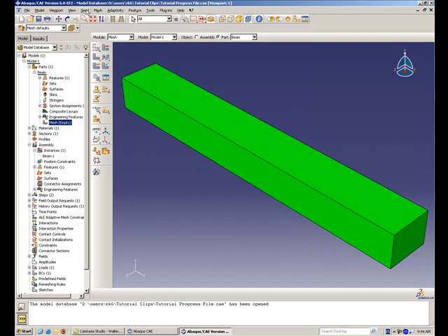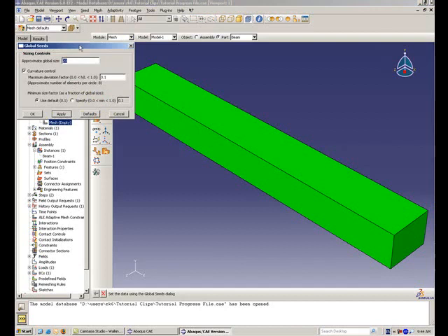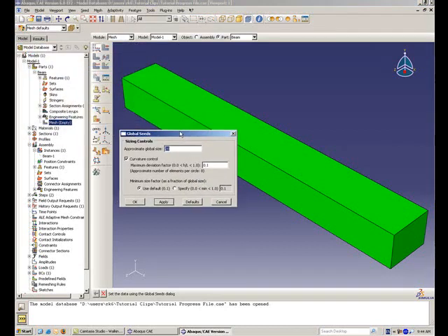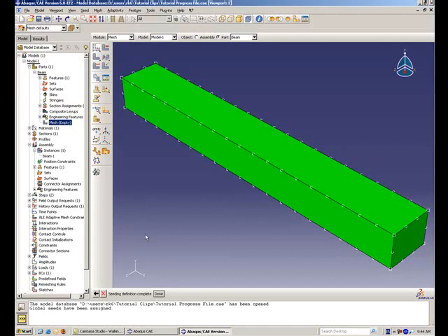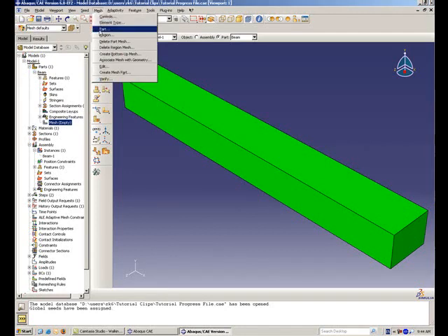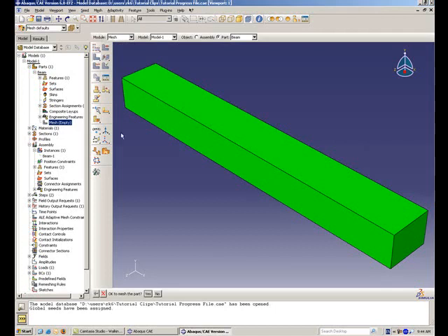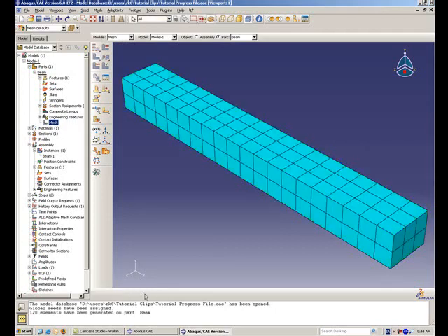Now you've selected the type of mesh you want to use, click Seed and then Part in the main menu bar. Enter an approximate global element size of 10 and click OK. This tells Abaqus how large the default element size of the mesh should be. Click Done in the prompt area and select Mesh and then Part. Click Yes in the prompt area and Abaqus meshes the beam. The model is now ready for analysis.